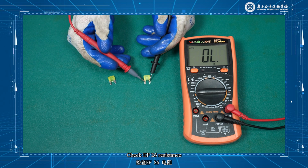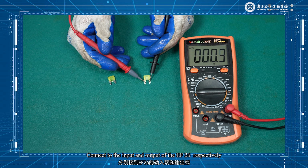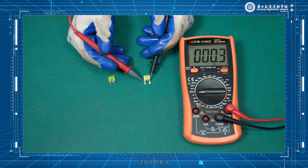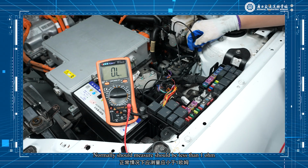Check EF26 resistance. Place the red and black pins on the input and output of the EF26 respectively. Read the resistance value. Normally it should be less than 1 ohm.